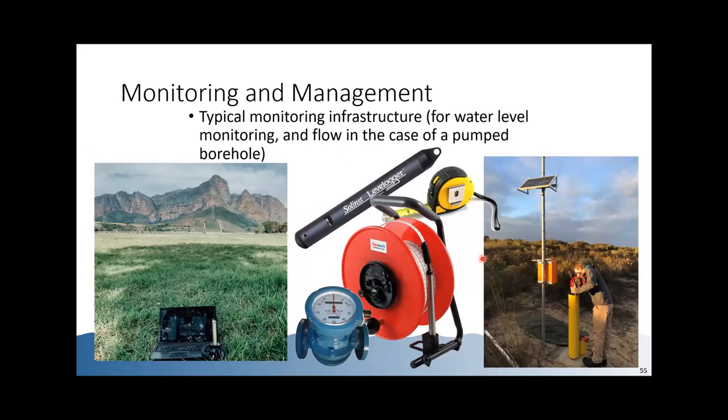Then when you go to your borehole, what will you need? As a minimum, you will need a dip meter. And this is quite a nice fancy one in red here. You get much simpler, cruder designs. What you want to do is to be able to, at any point in time, go to your supply source and measure the water level. If your borehole stops pumping for some other reason, if you can't measure the water level, you don't know if the water level has dropped to pump inlet or if it's the electricity that's gone off. You need to be able to measure the water level at your borehole.